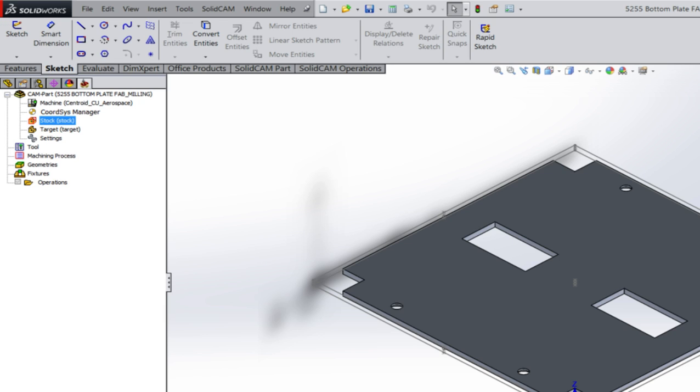So why don't we use like G56 for you guys? Are you on copper? We're on copper. You're on copper as well? So let's use G57. So you're 56 or 57. Who's on Vail? You are. So let's use G55. Who else is on Vail? G56. And are you a third group? Yes. G57. And then nobody's on Wolf Creek in here? I think that's Aaron's group. Okay. So on Wolf Creek, that controller does not support multiple coordinate systems. It only has one. So you need to be in G54. Just so you guys know. Okay, so that's assigned.